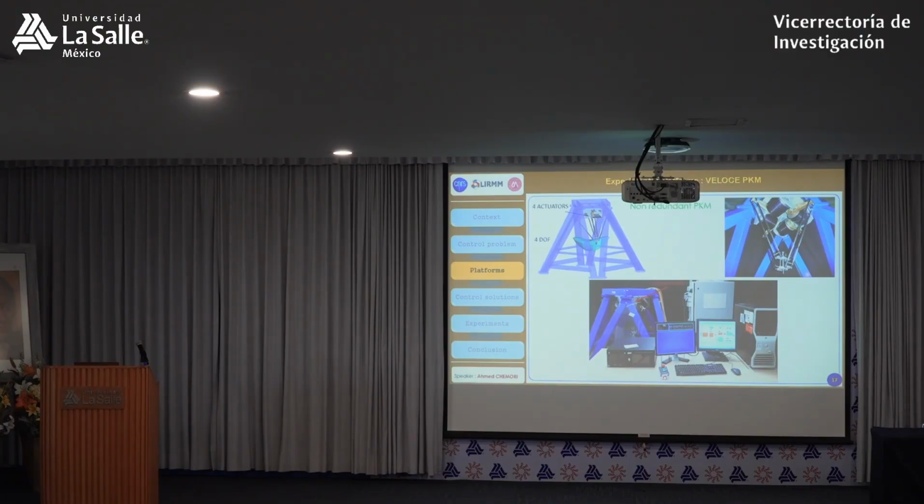If you take the other applications, waste sorting is the same. Suppose I take a box, I want to put it for plastic, for instance. When you take the bottle you don't know if it is empty or full. You understand? I take a bottle like that and I want to put it in a box. I don't know the mass, I don't know the inertia, I don't know if it is full or half full or empty. You understand? And this is an uncertainty. And this justifies the development of robust or adaptive controllers.